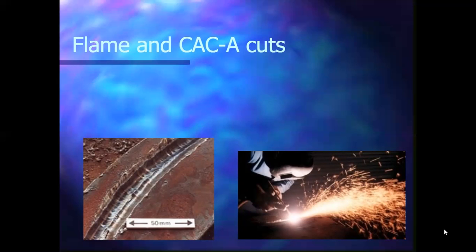The gun, or the electrode holder, that that person is using has a big red handle. It's like a regular electrode holder, but bigger. And beneath that rod, which it actually uses, just like welding, but a different type of rod, there are three air jets that go underneath it. When your rod heats up the steel, the air jets blow it away. That's why you get that big flying arc of sparks. And on the left, this is what your cuts are going to look like if you're using a 1/4 inch round cutting rod. So that's pretty cool. It's a neat setup. I've used it a ton. It's great for fixing things like cracks or cutting out welds on something that has to be removed. I used it a lot when I was doing repair.